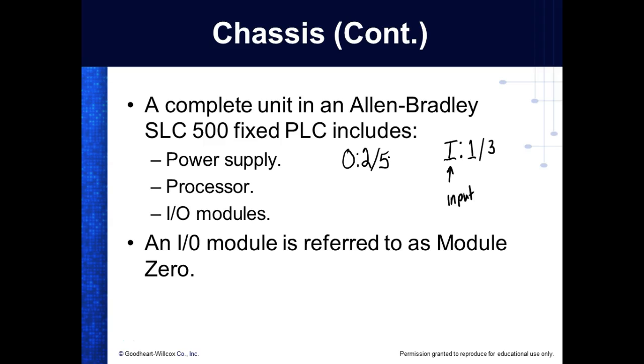I'm not going to show you Siemens, you'll get confused right now. But I do like Siemens. Allen Bradley uses O, so it gets people confused because they'll hit the 0 key a lot, and then, of course, you'll get a syntax error. What Siemens decided to use for outputs is Q when you address the outputs. So you can't get a Q confused with an O, right?